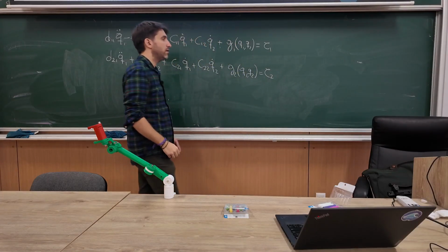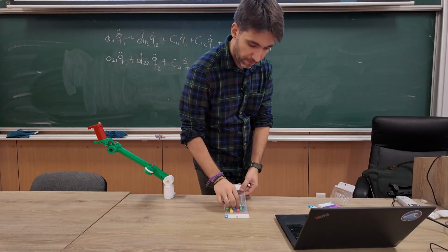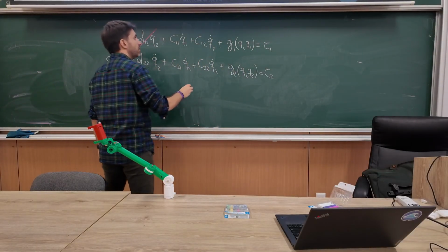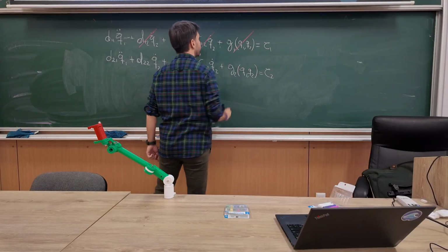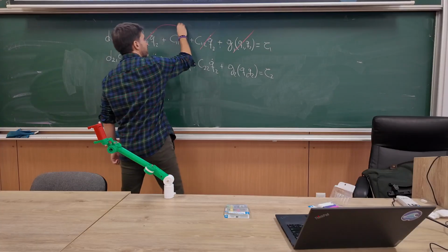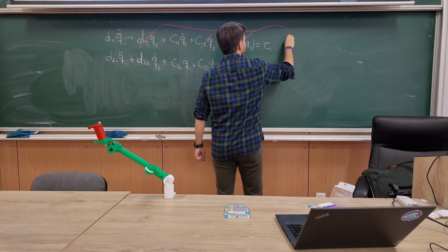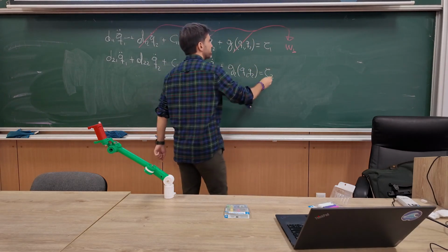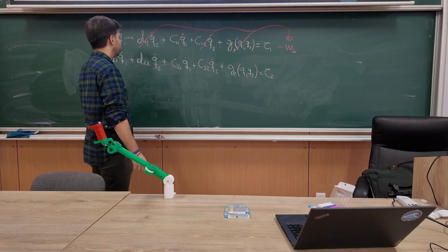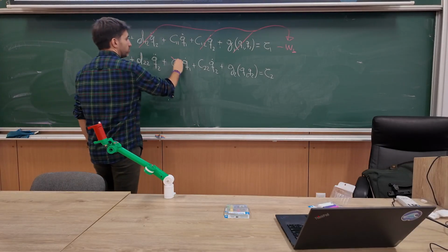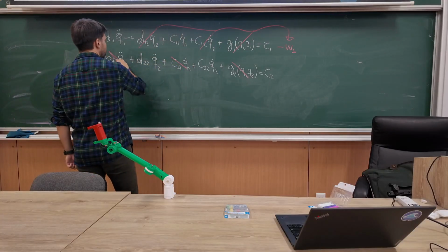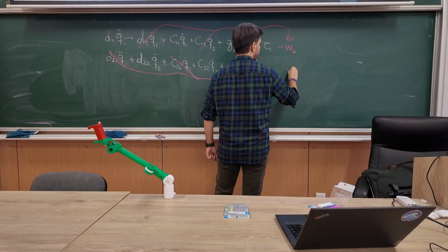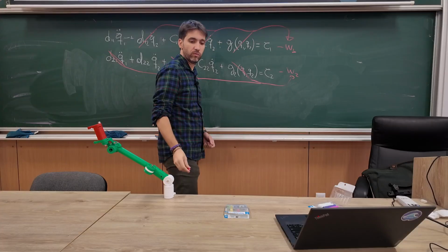This should be 1, this should be 2, q1 q2, tau 2. So what I'm saying here is, for the first joint, I will neglect this one and this one and this one, right? I will not totally neglect them, but I will add them up and put them here as disturbance 1. And because they go on the other side, it will be with a minus. All right? Similarly, I should do this for the other joints. I take these three and call this w2.